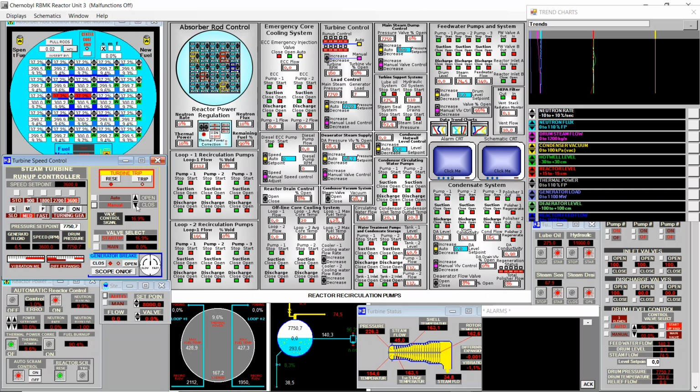So this is more or less the load that we need to spin it freely, like accelerating a car just to keep the engine running in idle or in neutral in the gearbox. But we should be very careful, because as I said before, if we go below 0, we will have a reverse load and this will cause a turbine trip. So let's continue, keeping an eye on the generated load and the startup position.